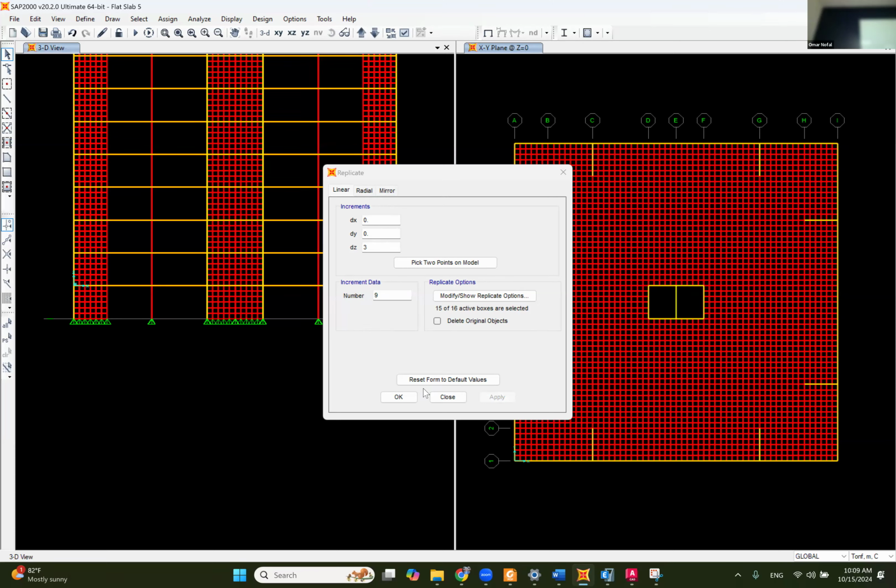If you look at the seismic load combination in the ASCE 7-16, you'll find that you have to put earthquake in X and 30 percent in Y, and earthquake in Y and 30 percent in X. So every time the column is exposed to lateral moments, Mx and My. One of them is big and one of them is small. Okay, so you have the two moments on the column. So we need to take this column to another software or maybe manually to design for biaxial bending. So it's not hinge or fix, it's just how much moment this column is absorbing.